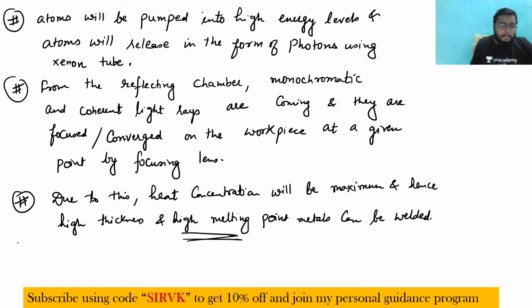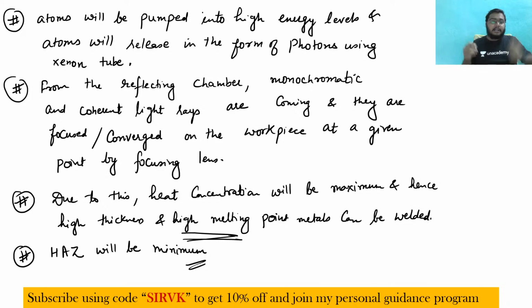And see, my dear friend, since these beams, these rays are very much focused, the heat affected zone will be minimum. Yesterday I showed you TIG welding, MIG welding, plasma arc welding, electron beam welding, laser beam welding, and the weld area that they cover. In that figure, I had shown that electron beam welding has a very good focusing and the weld area is very small.